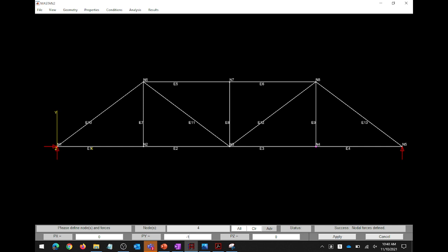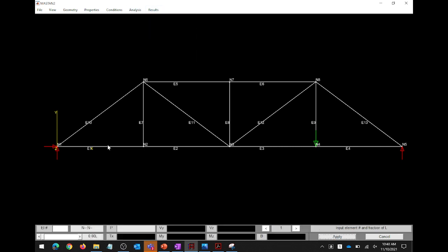So let's put the load there on that last joint. Well, look at that. 1/3. Okay? The diagonal, something interesting happens with diagonals. We get negative 0.4167, and then this compression member, negative 2/3. Does everybody follow along with what I'm doing?